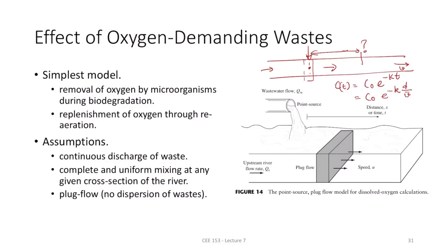Now the difference here is that K is the rate at which the BOD is being consumed, or the dissolved oxygen is being used up. But at the same time, one thing we haven't discussed yet is the amount of oxygen dissolved back into the water because of aeration. So let's see that one.